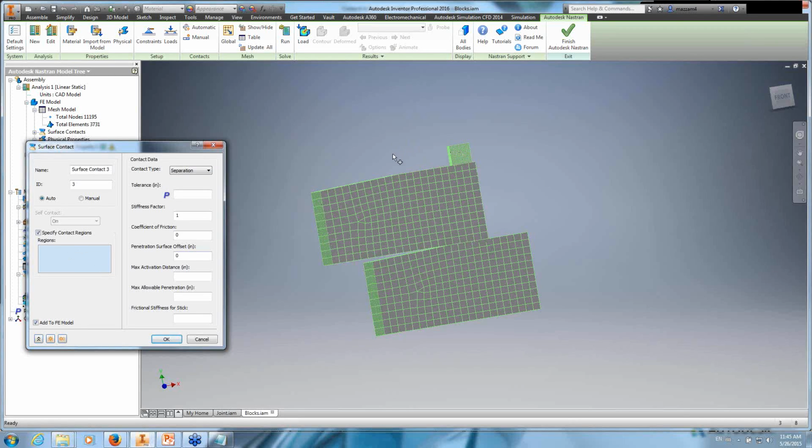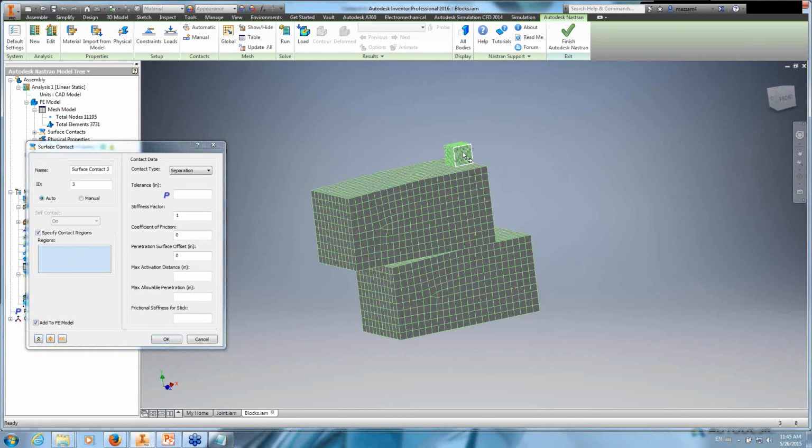Really, you would have to do it like this, because if you click on something, let's say we want to specify the first entity of the contact, I'm not clicking on the entire body here. I'm either clicking on an edge or on a surface, but if I right-click on it and select other, then solid becomes an option that I can select.